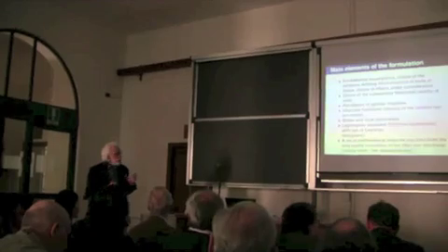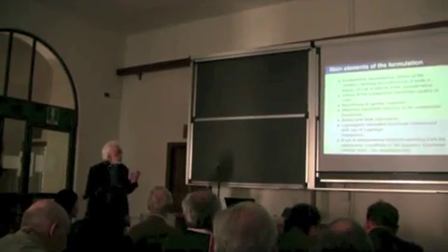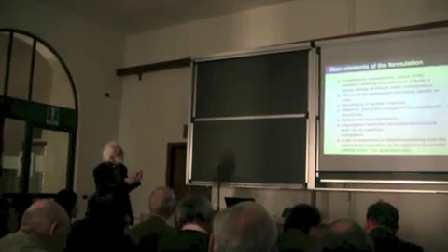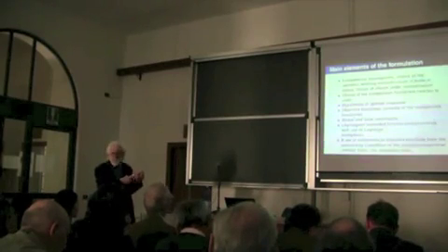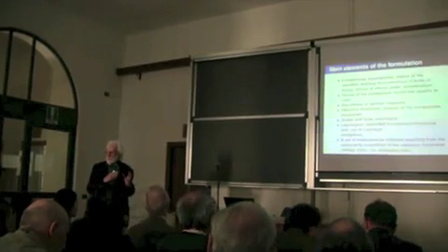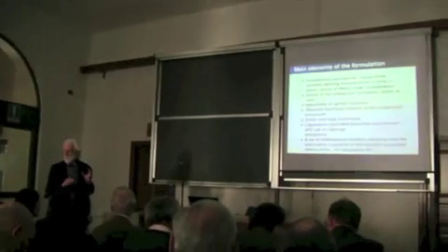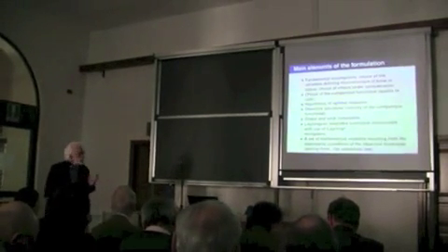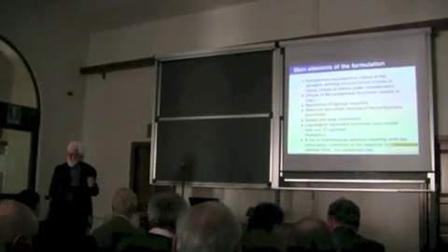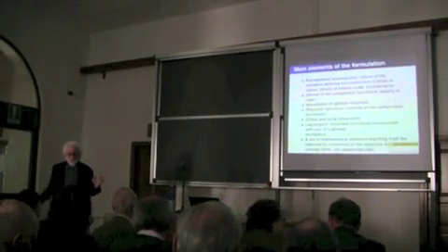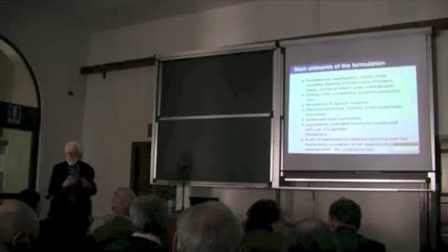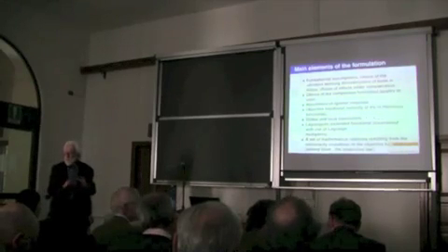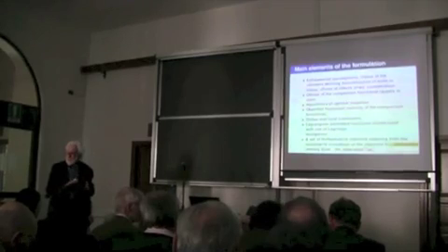Then we build the functional, which is the rate of the comparison function, I mean the time derivative of the comparison function. And from the necessary condition of the extremum of this functional, we get the set of equations, among them the equation which is called adaptation law.